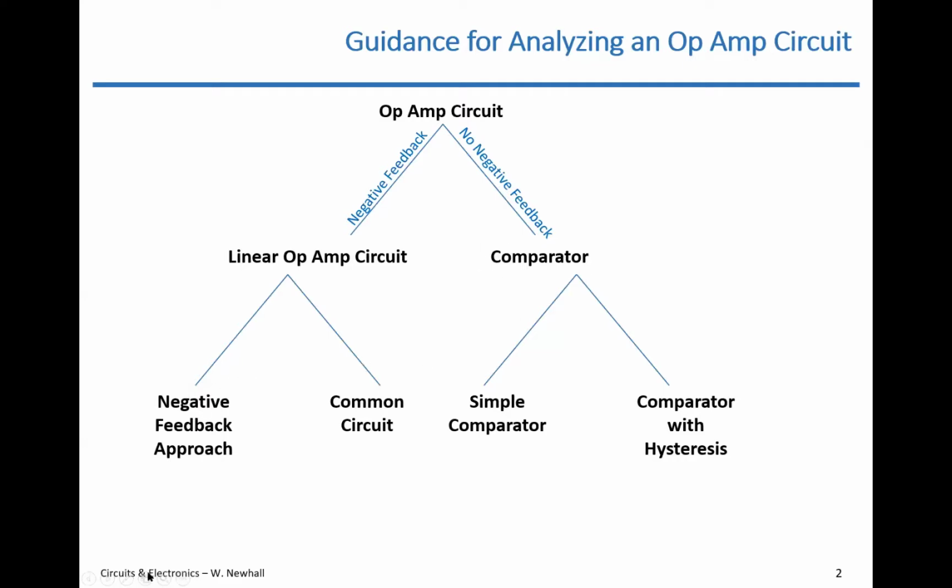And then just to review at the bottom, what we're doing when we look at a linear op amp circuit is we're deciding, well, do we know the circuit? Is it a common circuit where you know the gain? And if not, you use the negative feedback approach.